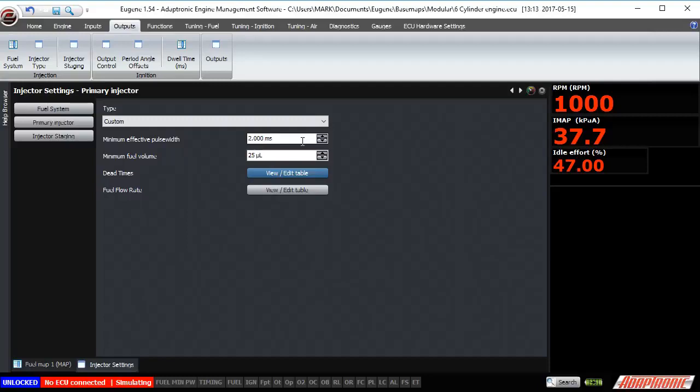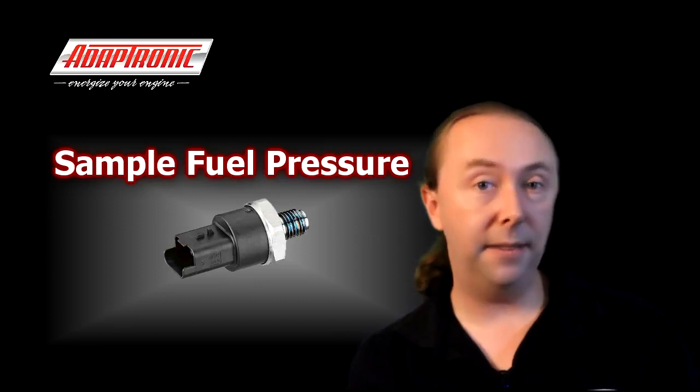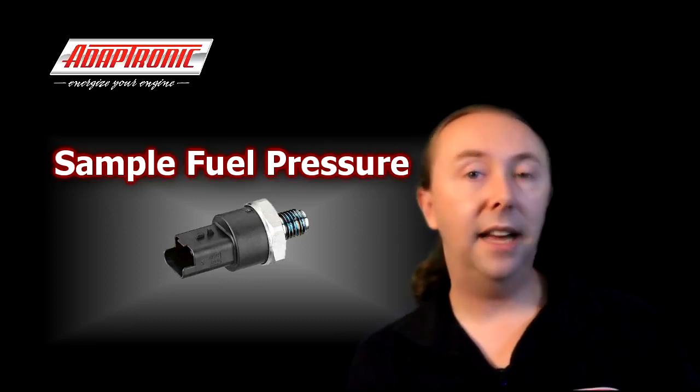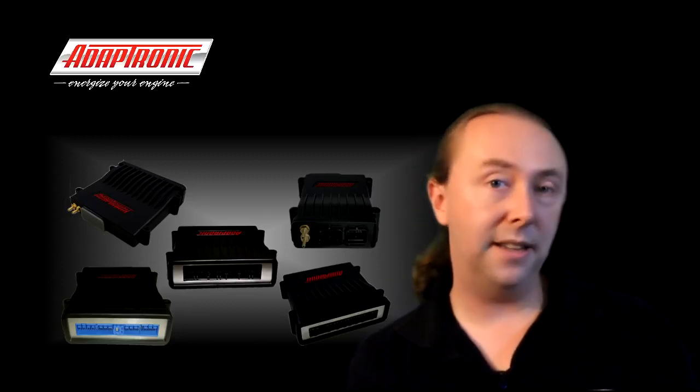Now next, the ECU has a 3D table of offset, or dead time if you like, which is the x-intercept on that injector graph I showed you before, which is a function of battery voltage and fuel pressure. Now note again, this is a differential fuel pressure, so this is the pressure across the injector. And this can be determined in two ways. The first way is to measure it directly. So for this you'll need a fuel pressure sensor, and the ECU will subtract the manifold pressure from the fuel pressure to work out the differential pressure.